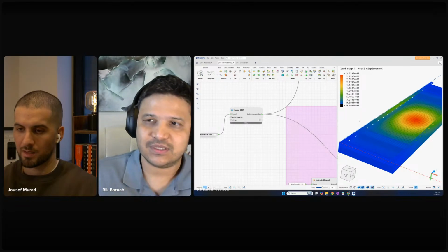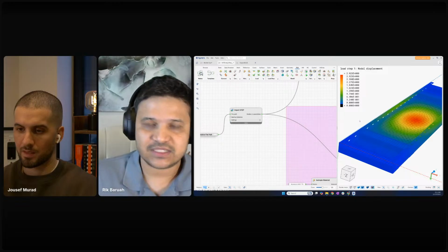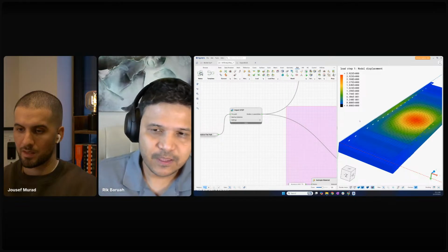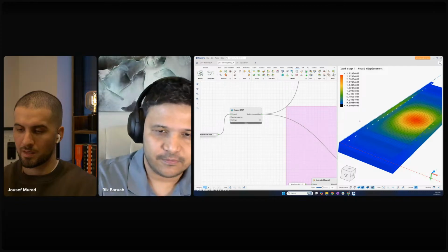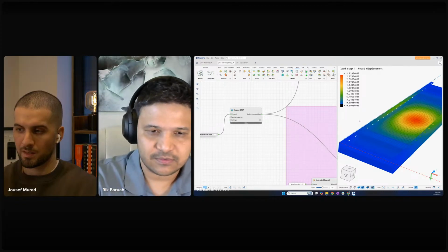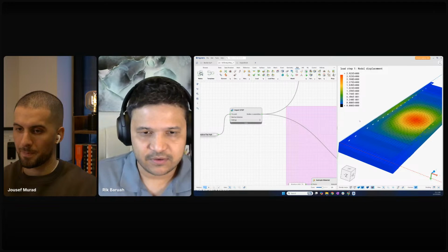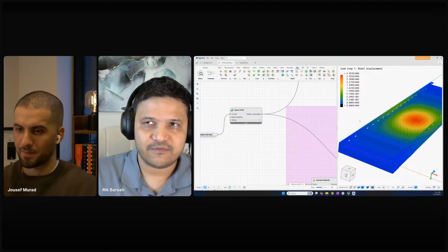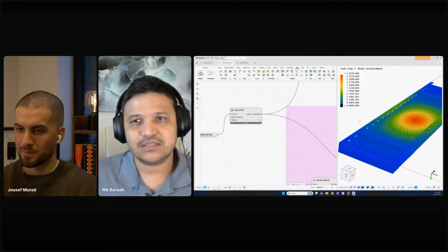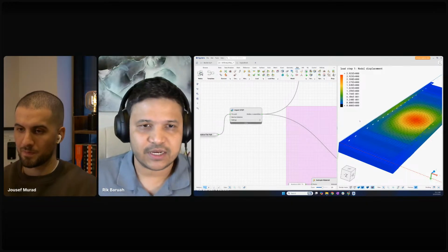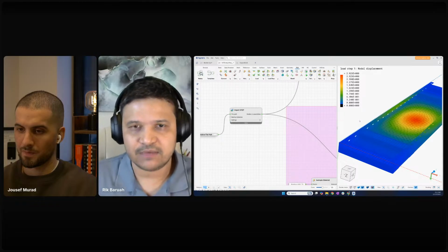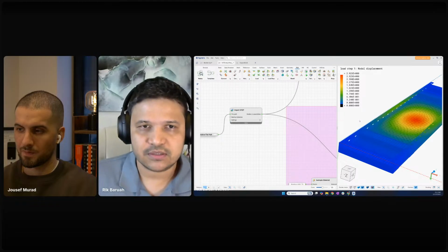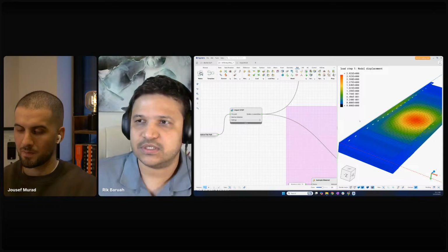Our Intact technology is based on classical FEA methods, where we use the same classical methods in performing FEA on the non-conformal mesh. What we do is mesh the space around the geometry. This allows us to take the geometry in and out, put in a different geometry, and keep the same boundary conditions and properties.